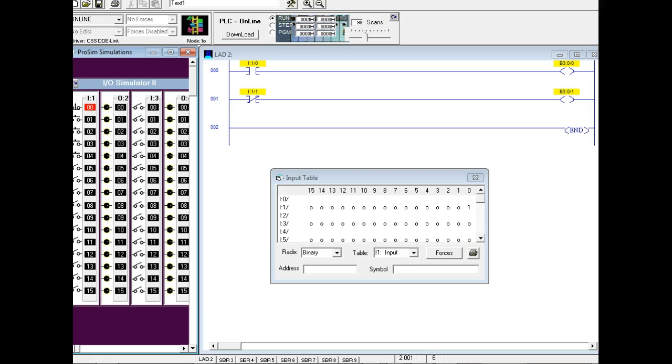You keep saying switch, but what can we hook up to these inputs? We can hook up anything that gives us a signal, right? We're looking at nothing but push buttons, but in the automated line we went over there to, what did you see hooked up to the inputs of those PLCs? All kinds of stuff: limit switches, photo sensors, metal detectors, capacitive sensors, ultrasonic sensors. They were all hooked up to them.